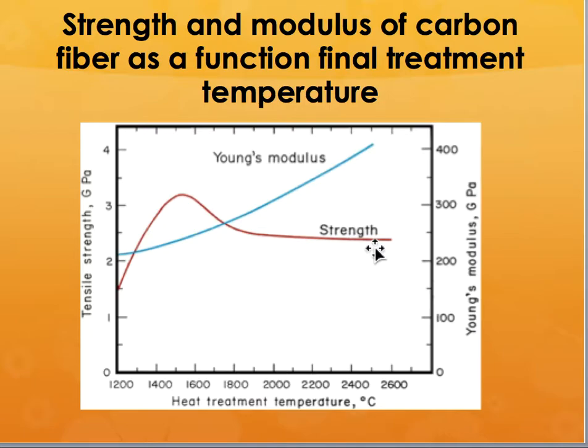And now there are other techniques that people are using nowadays in order to get really high strength and high modulus carbon fibers, that is based on carbon nanotubes. So you pull the carbon nanotubes, and as soon as you are pulling it and graphitizing it, you get really high strength and modulus at the same time, but they are more expensive, obviously.